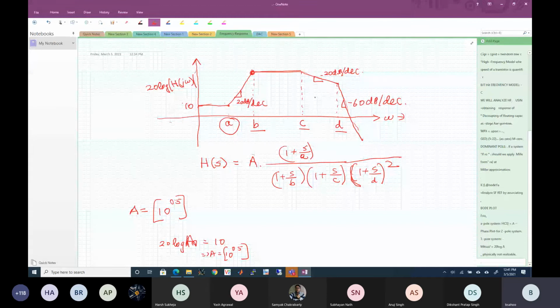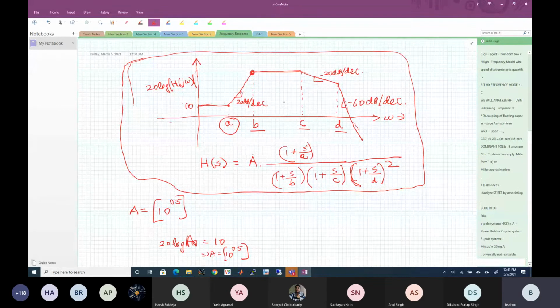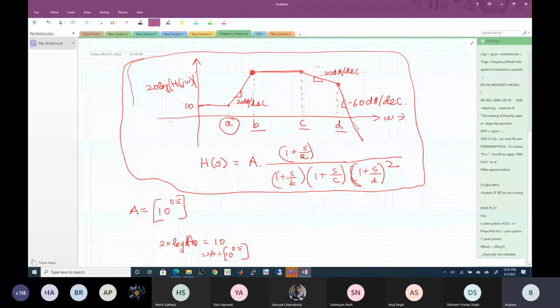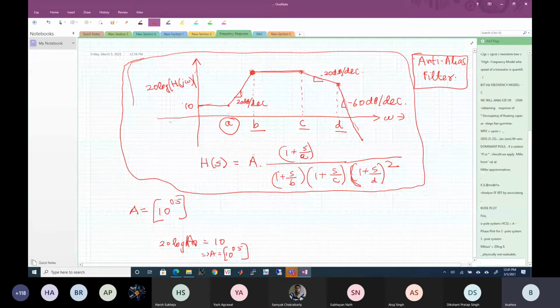And this is how filter design is done. All the filters in the world that you are using, you decide on the Bode plot first, then you decide the size of switches and resistors and capacitors to get exactly the poles that you want. In all the cell phone reception there is something called an anti-alias filter, which is there in all the cell phones, computers, everything. In any analog system, it is there. And this filter is designed by first looking at the bandwidth response and doing all this analysis and then saying, okay, I'll do it like this.